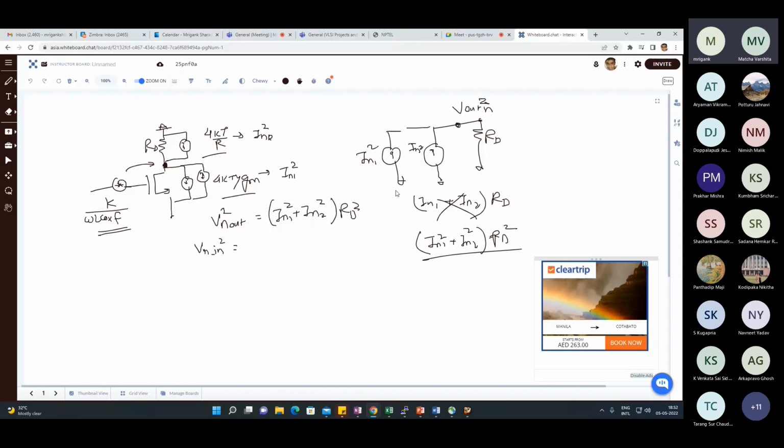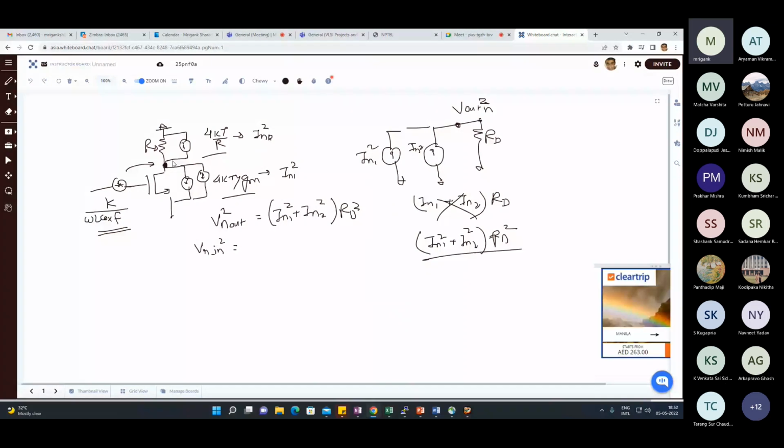Any question on this? The flicker noise is a voltage at the input, so we don't need to refer it, right? We can just refer the current sources. Yes, just for understanding: just like you have the other two current sources at the output, if you want to transform this also and see what the output noise voltage is because of this one, you can do that. Then the whole total expression is there, and to get the input referred value, you divide by the gain, just for uniformity.